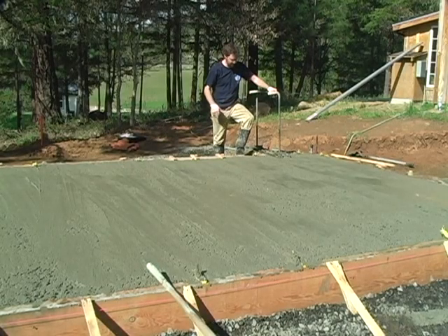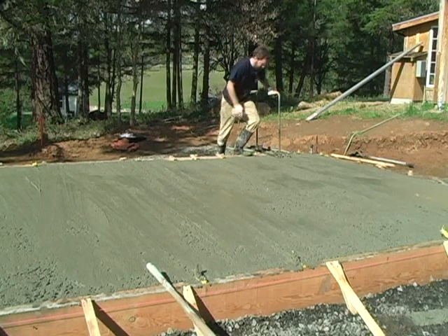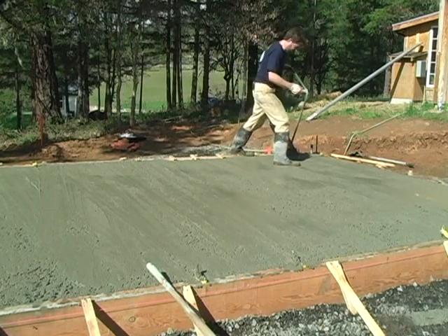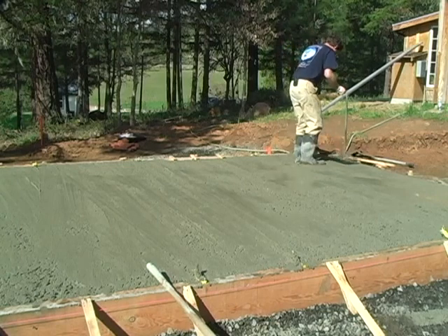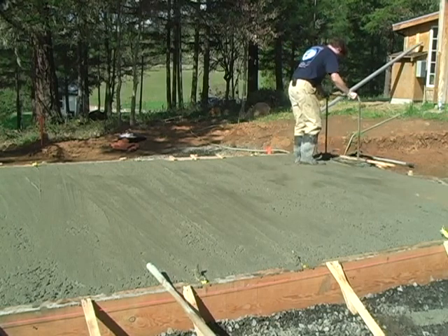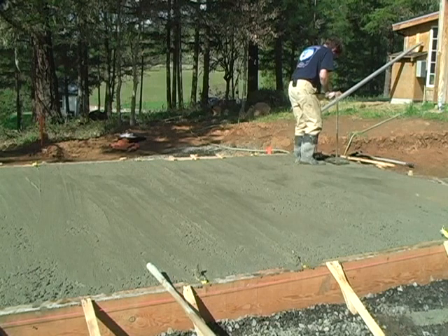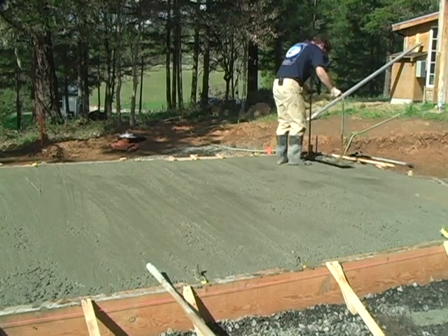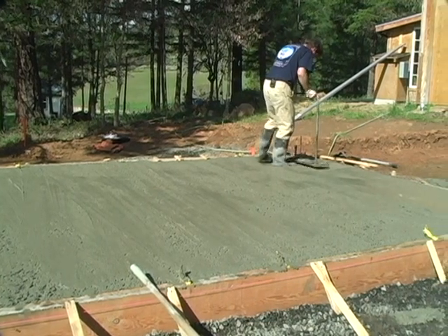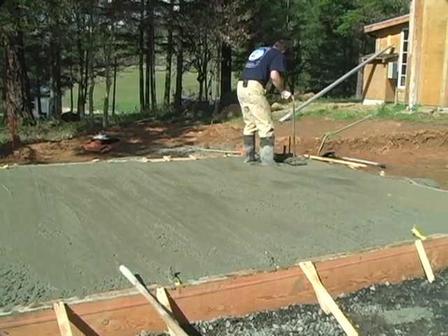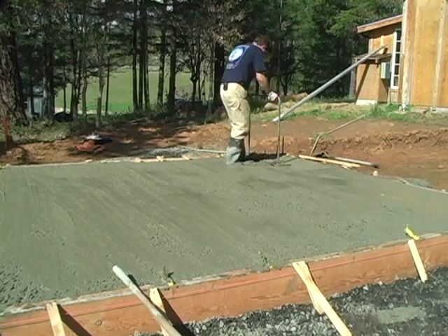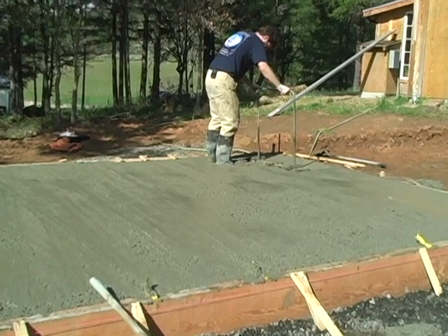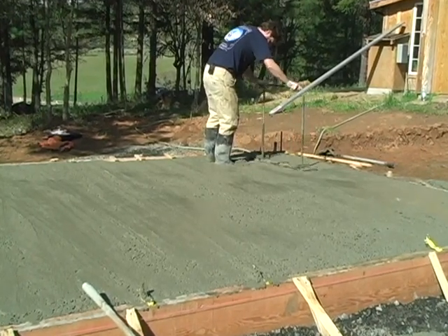With the jitterbug tamper, you want to just get right on into the concrete and step in here. You step out away from the foundation edge, because that's where you've got a lot of concrete and you'll likely sink pretty quickly. Now I'm just lightly tapping the surface with this and bringing up what I call the cream, and overlapping it and working it into the corners. This is also, look at your footprints. You know when you've got the cream up to the top, when your footprints have filled back in nicely.